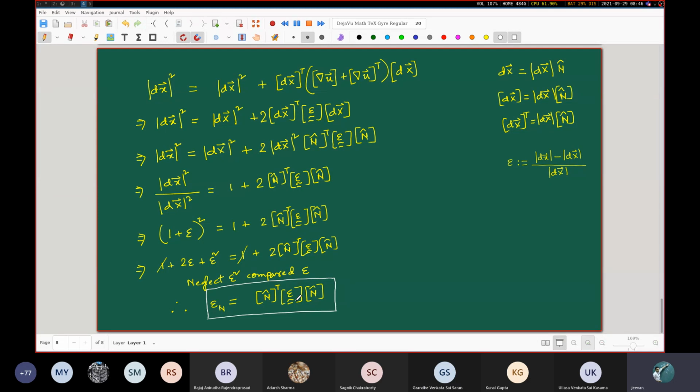There is always this big confusion whenever we try to draw an analogy between the strain and the stress. Earlier, when we were talking about stresses, we took this three-dimensional body and took a cut plane, saying that the unit outward normal to it was along a particular n hat. We considered the traction vector there, and then we took the component of it along the n hat, and we said that this component is what we'll call TNN. And that TNN expression we found exactly like this. So far, so good. Here also, you are trying to find the strain component along this n hat direction.